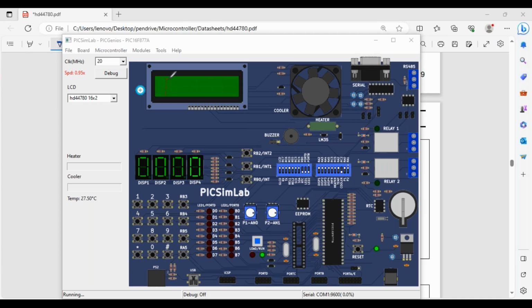I have 5 dots horizontally written for every box you see here. So if I use 5 cross 8 dots here, I can display one character here. I can display one more character here. 5 cross 8 dots, 5 cross 8 dots. One character up, one character low.